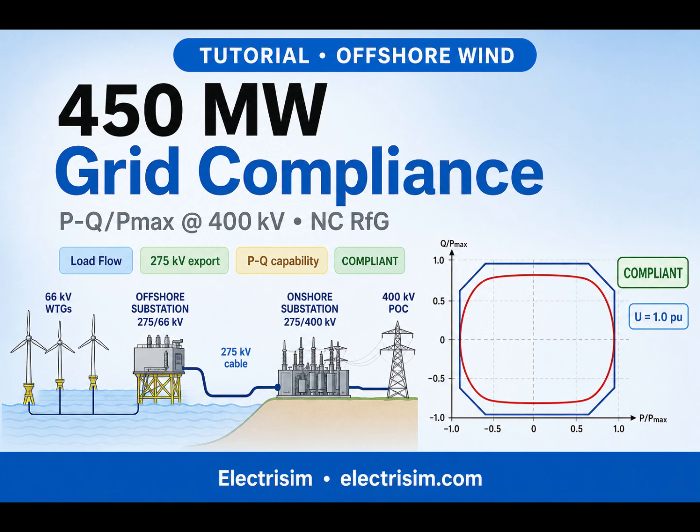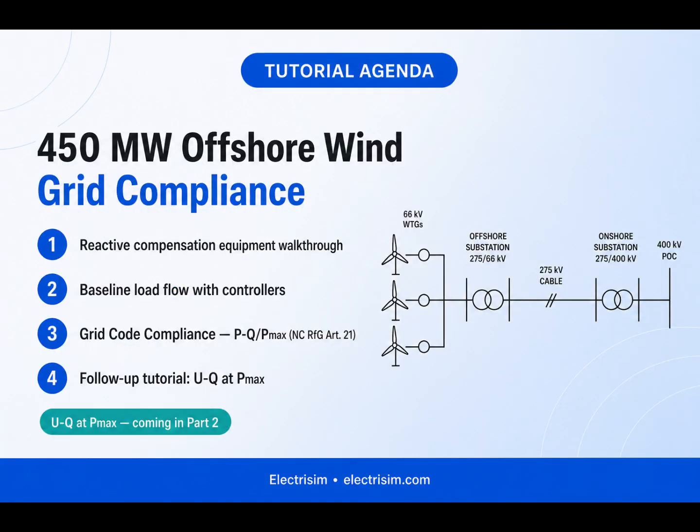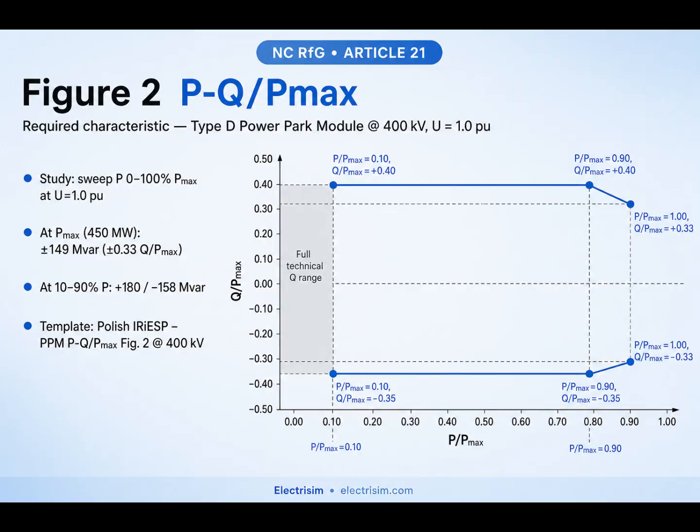In this tutorial, we use open-source Electrisim to study reactive power and voltage control in a 450 megawatt offshore wind farm. Then we verify the European Network Code Requirements for Generators, grid code compliance at the 400 kilovolt point of connection. The model is free, runs in your browser, and uses Pandapower under the hood. Validated against commercial tools like PowerFactory and SynerGEE.